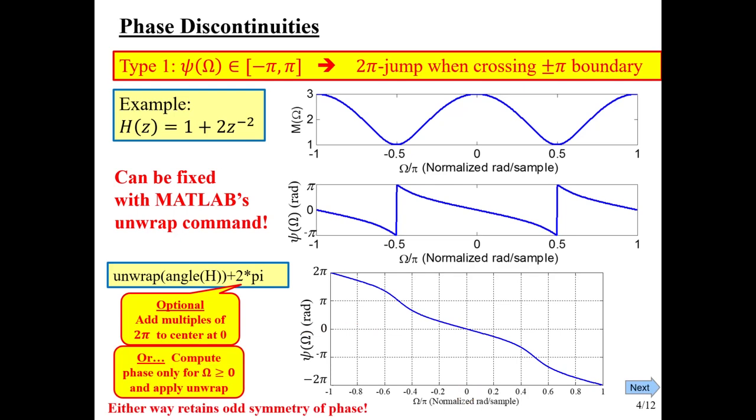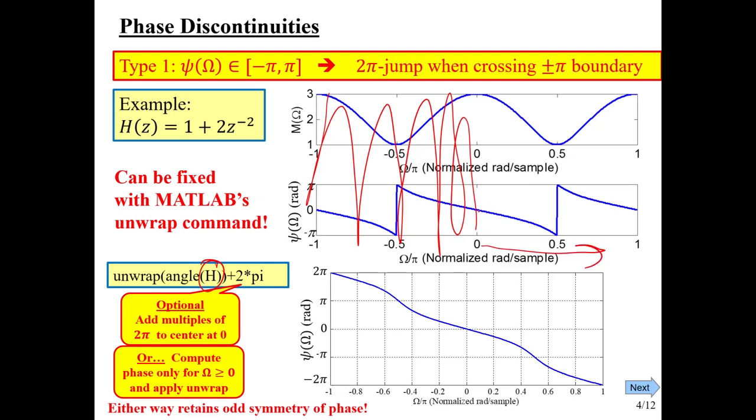Another option, though, is that in many of our audio applications, we don't do the negative frequency side because we know what's going to be out there. There's this symmetry, right? So we often just look from 0 onward in the positive direction. So let's see what would happen if we were to not compute this. So when we did freqz to get this H, we're not doing the negative frequencies. We're just starting from the positive frequencies. Note that that starts at 0.